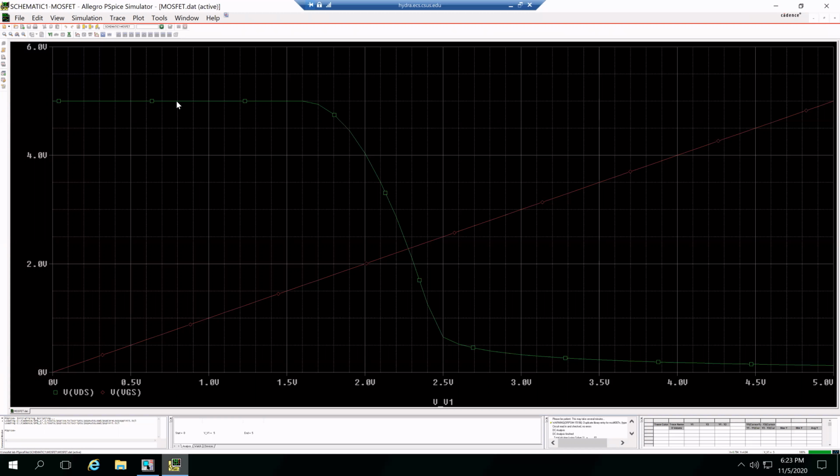You start accumulating a really big positive voltage on the gate, you get a bunch of electrons forming in the channel, and you get that channel formed between the drain and the source. And now you have a voltage controlled current switch essentially, to where as the gate source voltage gets bigger, more current flows through the device. As more current flows through the device, you get a larger voltage drop across that drain resistor, right?